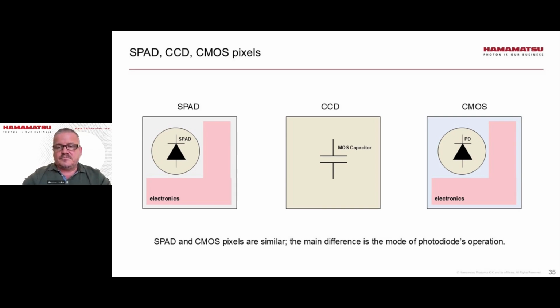Therefore, in CMOS, the readout noise is very important, and it's going to limit our ability to detect, for example, individual photons. It became possible recently to do that for certain types of readouts because the read noise has been reduced to a small value.